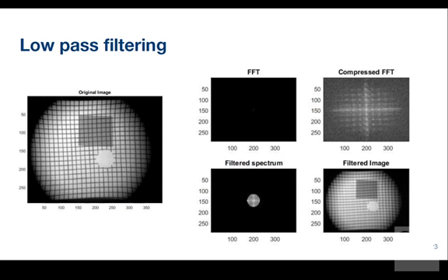There I've done the Fourier transform. We've rescaled it just for display purposes. Then this shows the filter applied to that. So there's the circular region. We're going to eliminate frequencies greater than this 0.2 of the maximum, and only allow the frequencies less than that. And then this is the filtered image. So low pass, remember, is going to be eliminating higher frequencies. So we're losing some of the resolution there, or some of the sharpness in the image, as well as eliminating any random noise which might be in there.